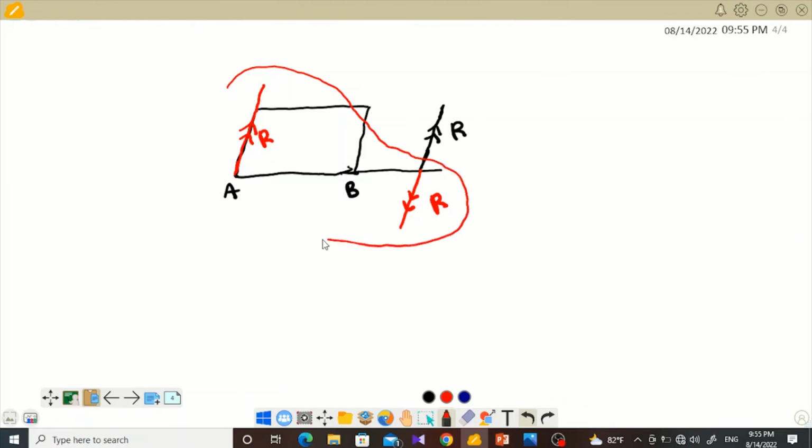By adding a couple, we move our resultant force to the given location, and we can find the value of the couple by finding the perpendicular distance r between the two forces. If we find the perpendicular distance, we can find the value of the couple.